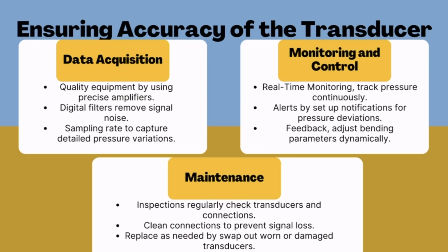We need to inspect regularly to check the transducer and connection. We need to clean connections to prevent signal loss, and we need to replace as needed by swapping out worn or damaged transducers.